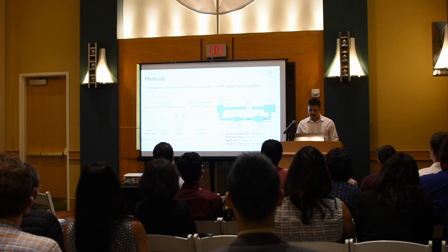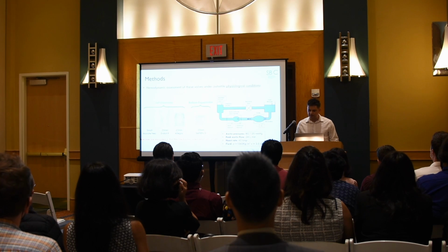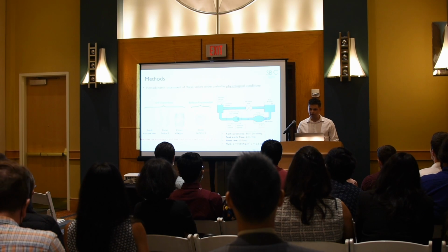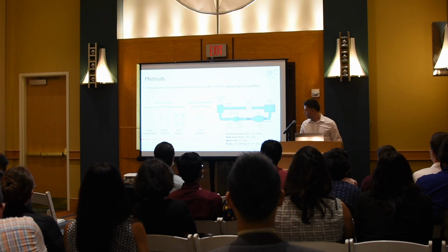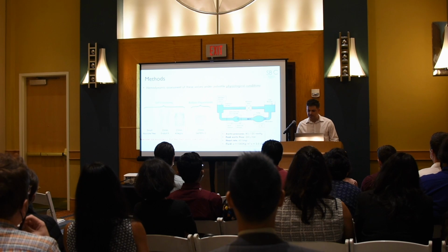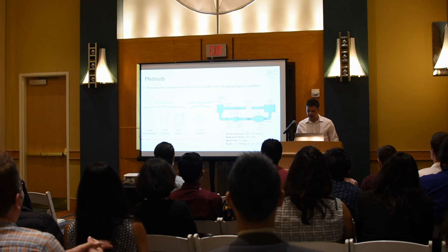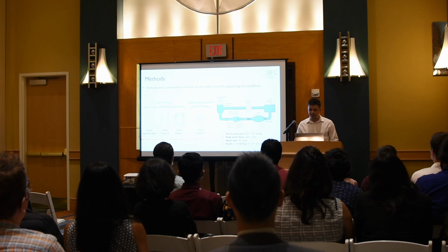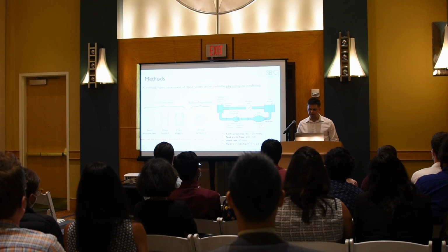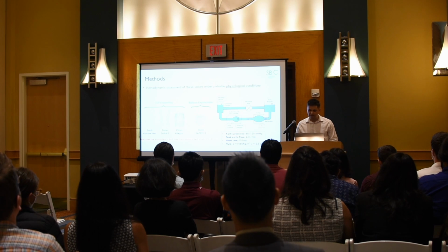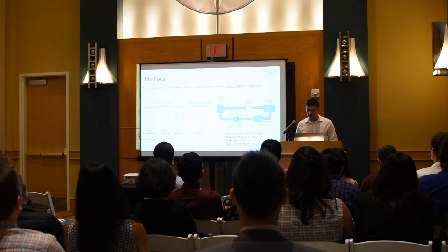For this study, the valves were implanted into a rigid test chamber, and the aortic pressure ranged from 80 to 120 mmHg. The peak aortic flow was set at 24 liters per minute, and the heart rate at 60 beats per minute. The fluid used in this experiment was a mixture of water and glycerin, 60 to 40 by volume, with properties similar to blood. And the valves were placed in the same annulus for all the experiments.